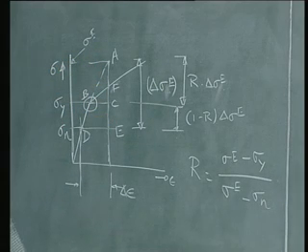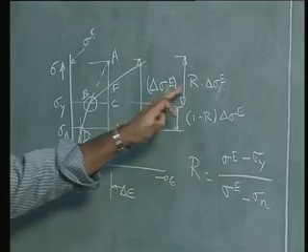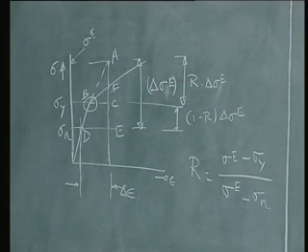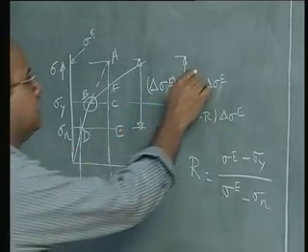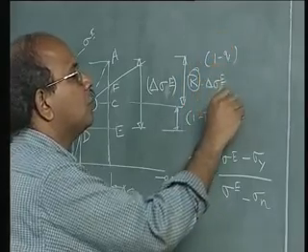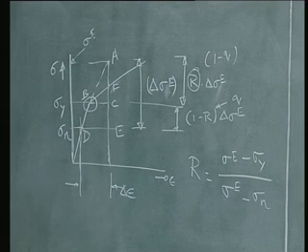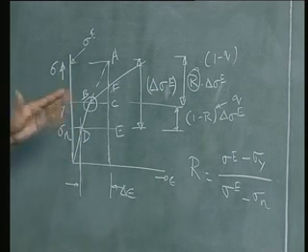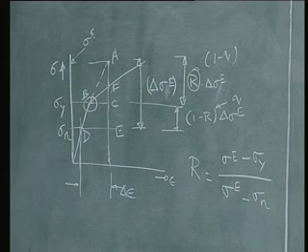So that part of the correction to the elastic predictor, delta sigma E, was written as 1 minus r, and that part which has to be corrected is written as r into delta sigma E. Various algorithms call this 1 minus r or 1 minus q, and this q, and so on. It does not matter. We may also shift 1 minus r to q and r to 1 minus q, but as long as you understand that of the total predicted stress I have to correct a part of it.